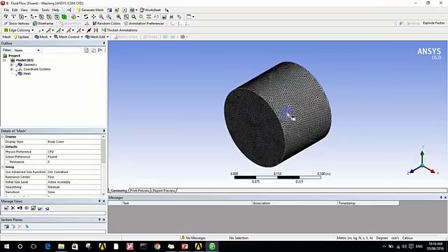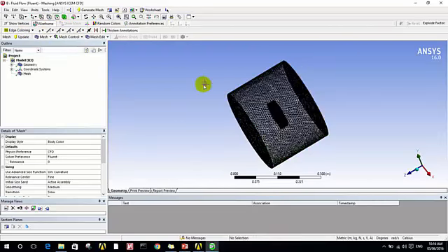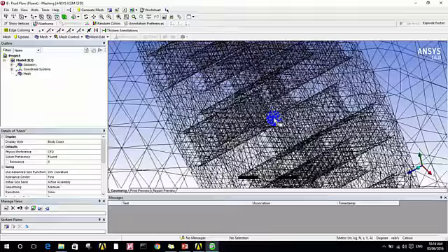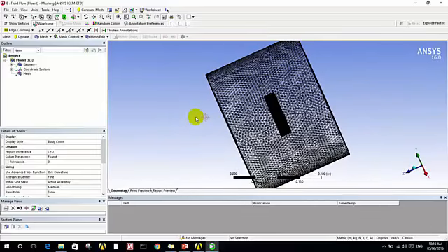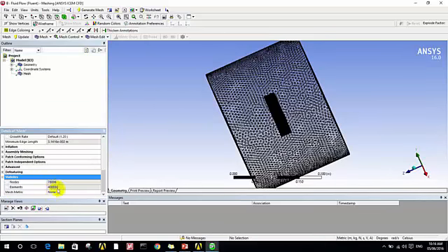Okay, I can see the inside by clicking on... no, not this. Okay. Now I see the mesh for the inside body and the outside, as we see, and these mesh nodes are the nodes that will be solved for this equation. If I go to statistics, I will see the number of nodes, the number of elements, and mesh metric.